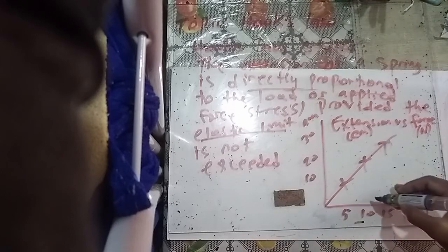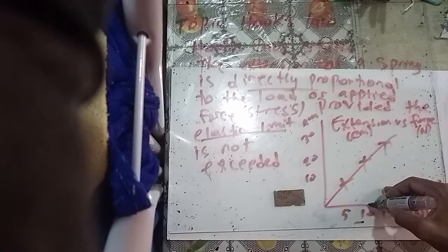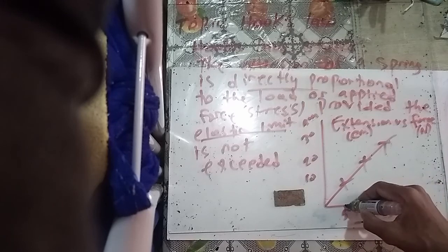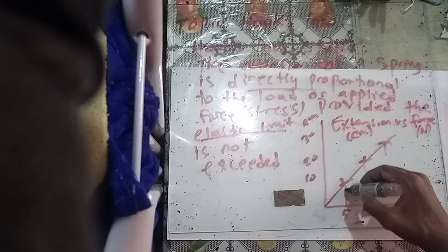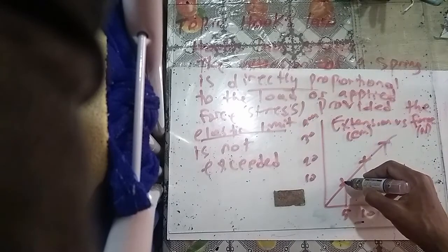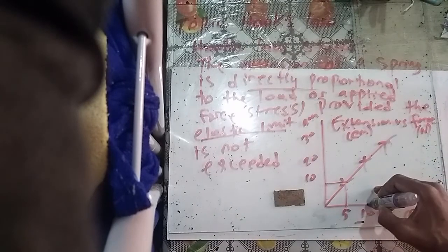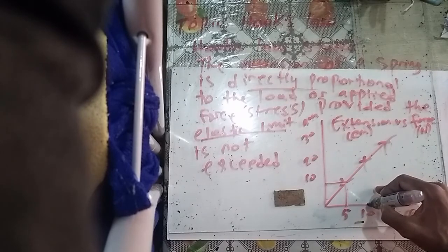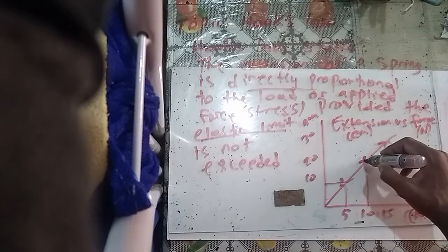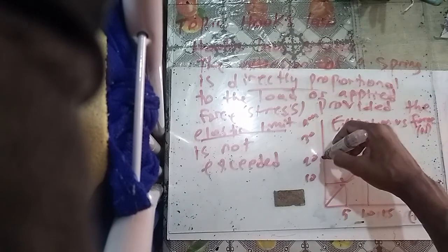So watch this. On a graph like this, the x-axis is in newtons. These are the forces that were applied, say from slotted weights, and this is the distances that were measured. Say I put a 5 newton force on it, I get a 9 centimeter extension, or 9 millimeter, right? I put a 10 newton force on it, I get a 20 millimeter or 20 centimeter extension, depending on the unit we use.